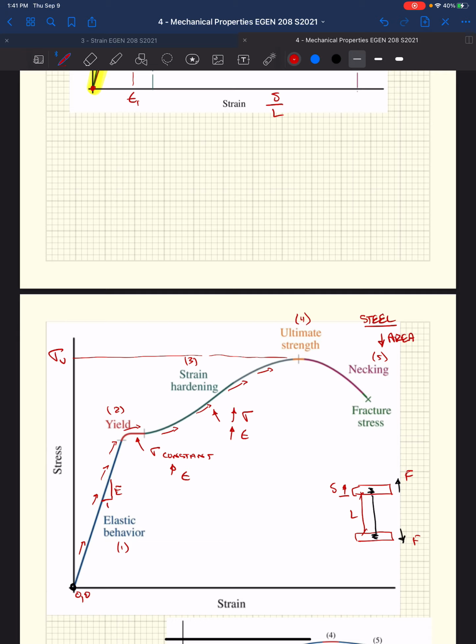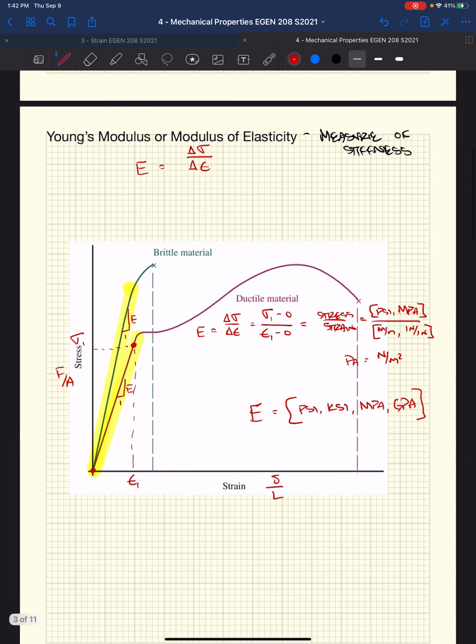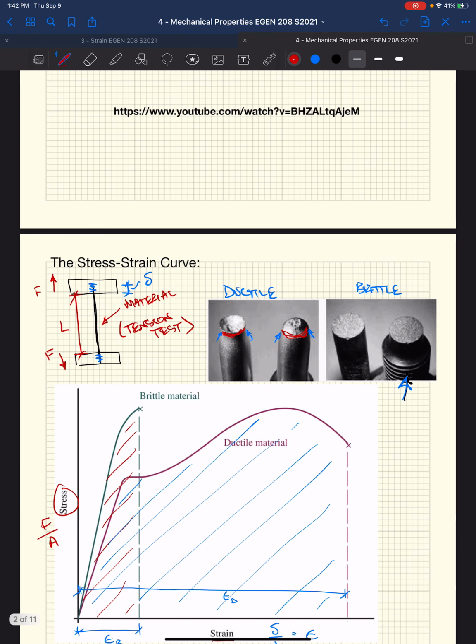And then at some point, it gets to a point where we hit our fracture stress, right? What we call here, this is our ultimate strain, or epsilon U, call this region 6. So that would be our fracture stress. At some point, it goes beyond its ultimate strain capability, and it fractures, just like you see here in our picture.